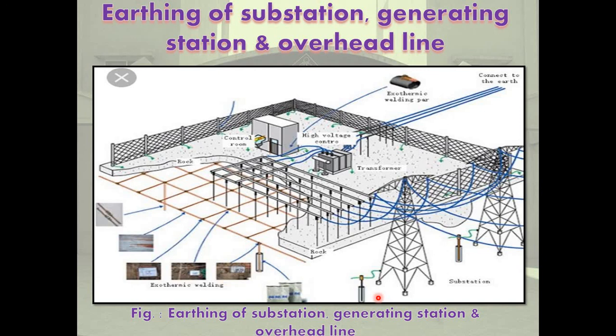Metallic switchgear earthing: various panels in the switchboard are provided with a common earthing bus. The earthing bus is connected to the station earthing system via two risers. A special earthing truck is provided for earthing the bus bars. The main equipment in the station earthing system: first is earthing electrodes or spikes.